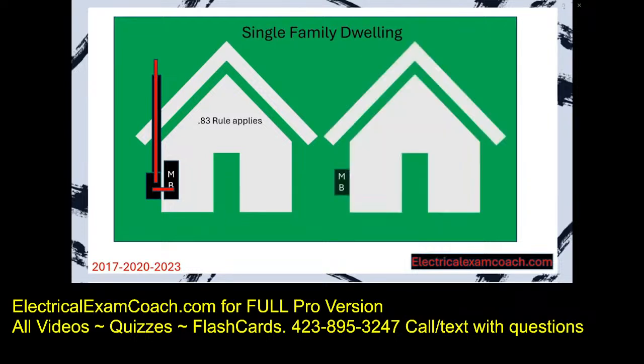Now let's imagine that we have a main breaker outside, we have the service riser, and we have a main sub-panel inside. We have the riser wire and the wire going inside. The 83% rule applies to all this wire. You can apply it to the wire going up the riser, and you can apply it from the meter disconnect combo to the first main sub-panel. Now the rule with this is that it has to be the panel that feeds the entire structure. You're not allowed to use it on other sub-panels or on any sub-panel that does not feed the entire structure. You have to be very careful with that one.